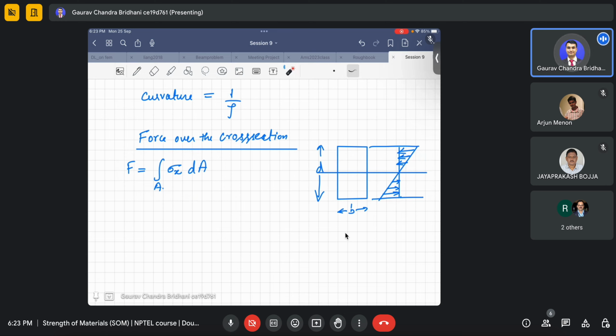So how to find that kd? He has used the fact that the force due to the concrete in compression is equal to the force due to the steel reinforcing bar provided. I would request, that is a very interesting problem and a very interesting application of composite beams. If you have seen it, very good. If you have not, you should go back and see that. It is in the second lecture.